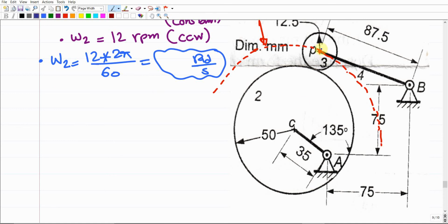Then your objective is just to make some connections here, to set up the loop as a direct contact. To convert this into direct contact, I can simply replace the roller by a slider. So I'm going to assume there is a slider, and this slider is going to slide over this curved path. This curved path has a center point, which is point C, and it has a radius of curvature rho. So how much is rho? It is essential to calculate this rho value. Simply, rho should be the distance between point P and point C. If you connect these two distances together, how long is this line? This line is going to be the radius of this big circle, because this is the center point of the same circle.